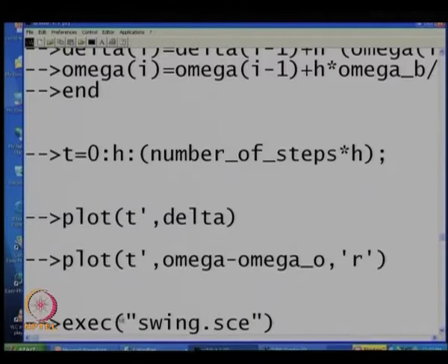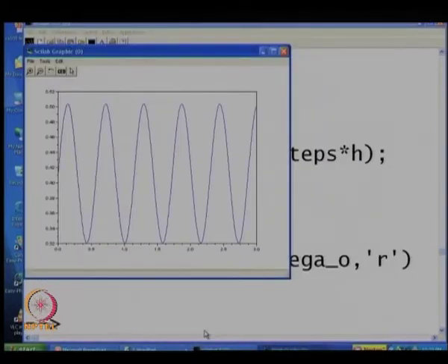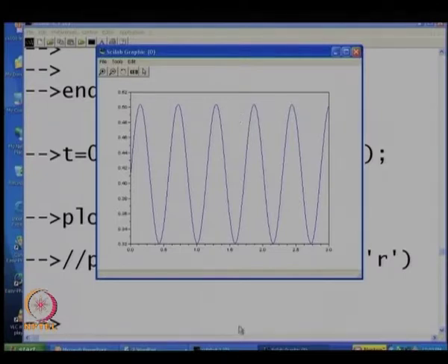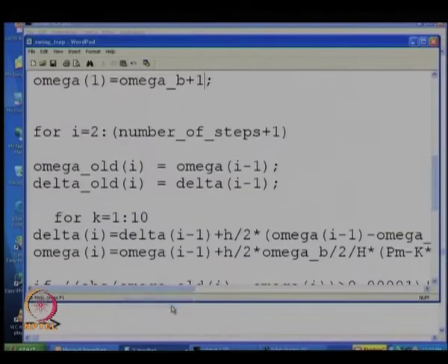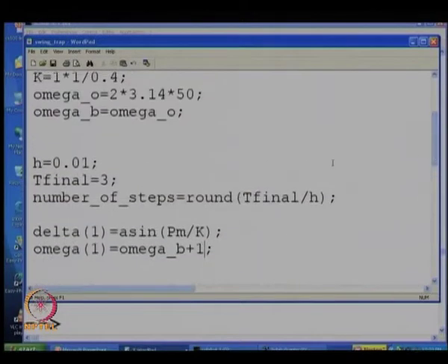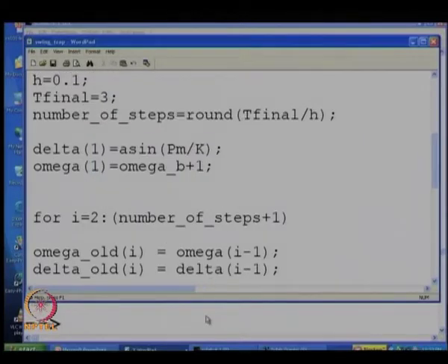Okay, we redo it, this is what we get with trapezoidal rule. Yeah, now we will get what we see. So, this is the response, and actually this sinusoid does not grow with time. So, this is in fact a really reasonably accurate picture of how delta varies if the system is given a small disturbance. Okay. So, even if I increase the time step, remember here, this will not really be affected. So, I just change my time step to 0.1, 10 times more, save this, rerun it.